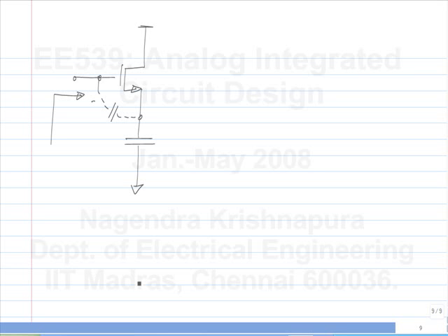So what can be a problem with this? If this is being driven by an amplifier, that amplifier is presented with some reactive load plus a negative resistance load. So with a negative resistance, it could potentially oscillate. For instance, the previous amplifier could be, in the worst case, something like this: some transistor loaded by an inductor. So clearly you make a nice oscillator using this one. So when you use it as an amplifier, it's a problem.